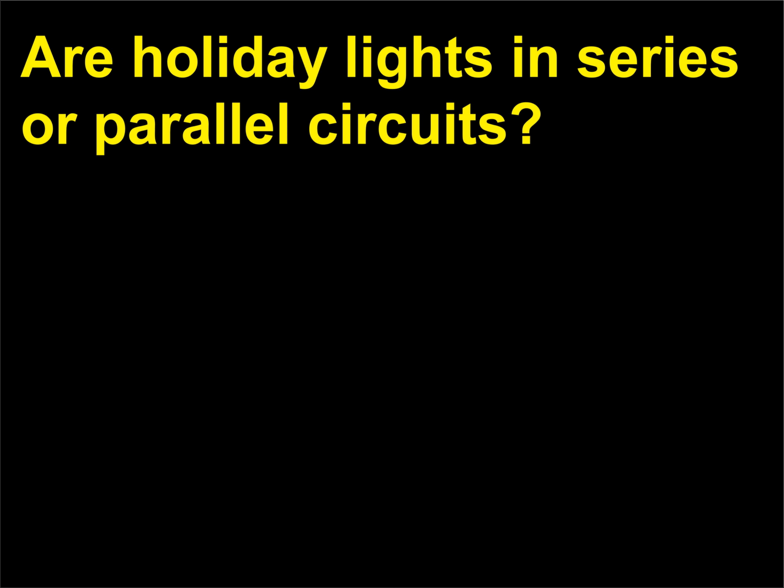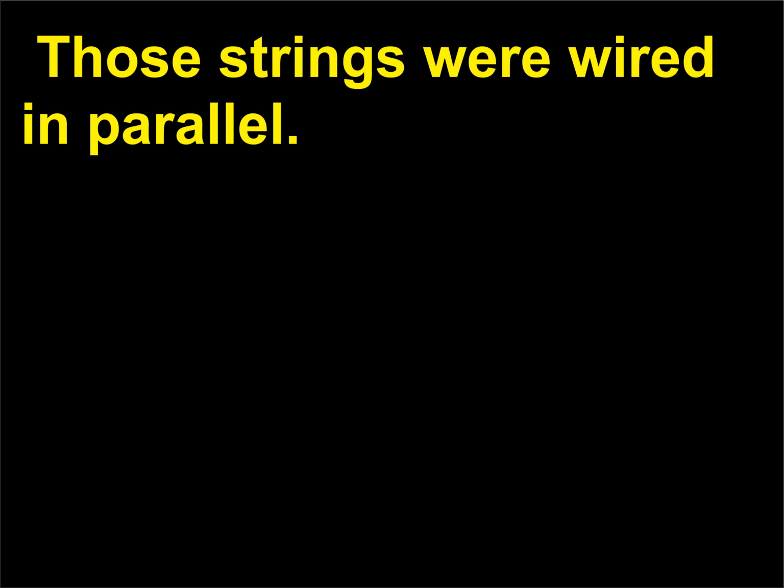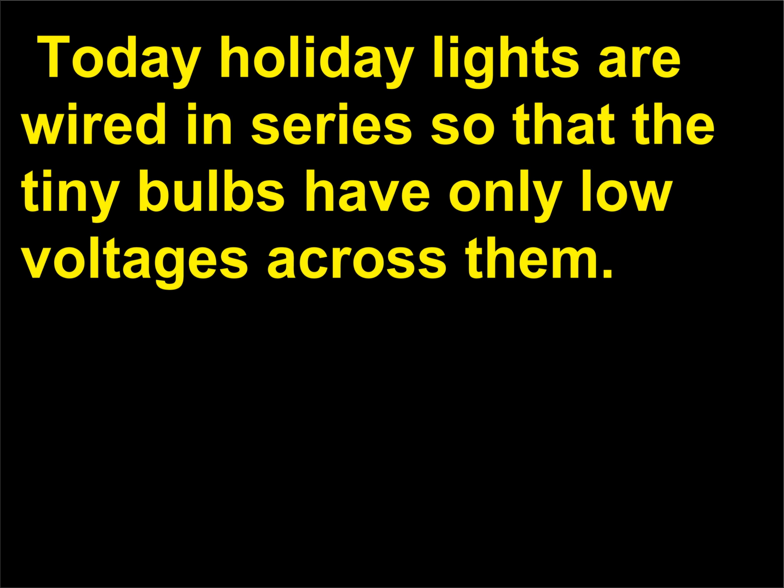Are holiday lights in series or parallel circuits? Many years ago holiday lights used large bulbs designed to work on 120 volts. Those strings were wired in parallel. Today holiday lights are wired in series so that the tiny bulbs have only low voltages across them.